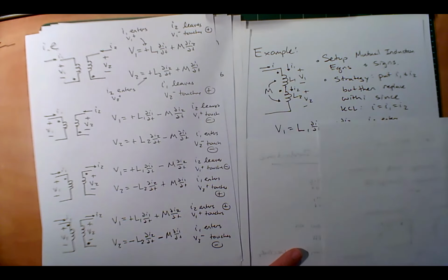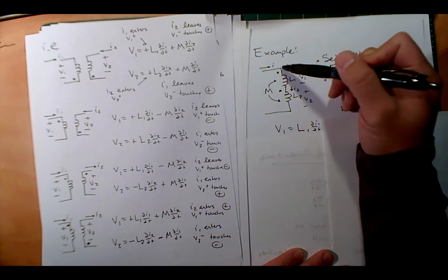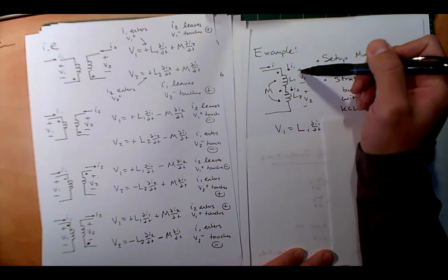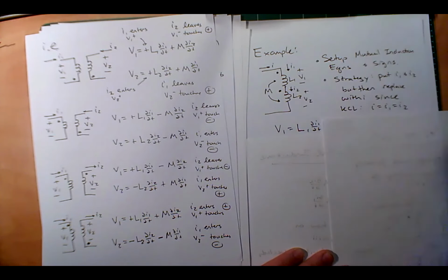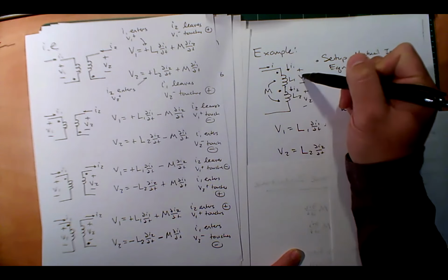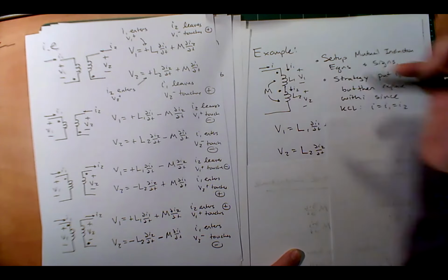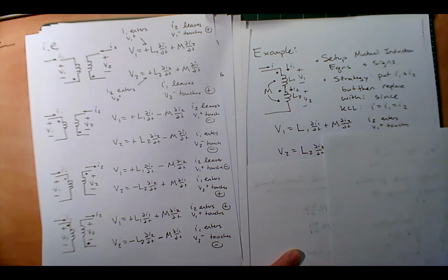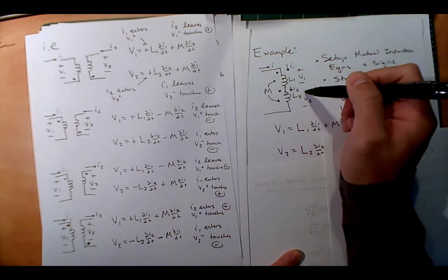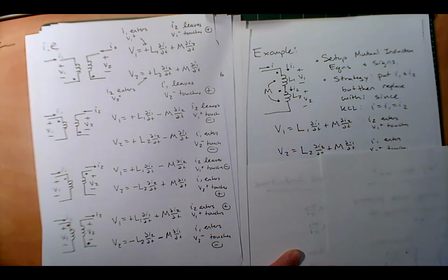Let's look at the self-inductance. V1, I1 is going to the positive terminal. V2, I2 is going to the positive terminal. So those are positive. Now I2 enters its dot and V1 positive touches. Good, that's positive. And I1 enters its dot and V2 positive touches. That's also positive. So this is like a positive all around case.